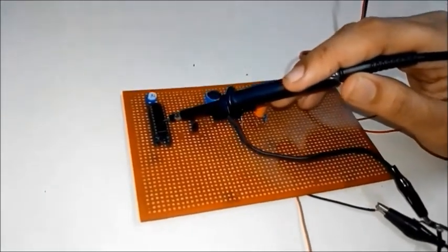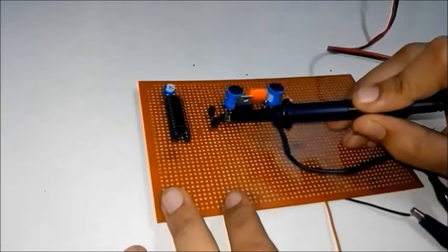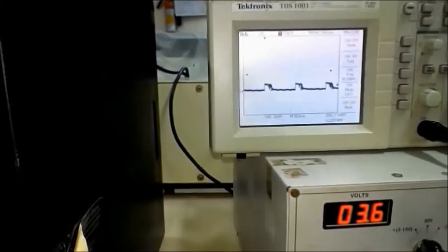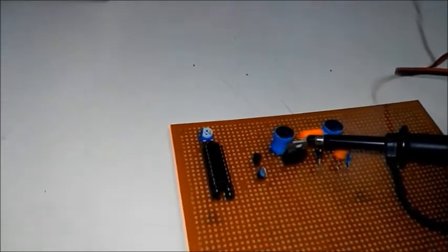Now we move on to the receiver part. This is the Texas Instruments MSP430. A PWM waveform of 12 kHz with the duty cycle limited to 30% is available at pin P1.6. You can see it in the CRO.